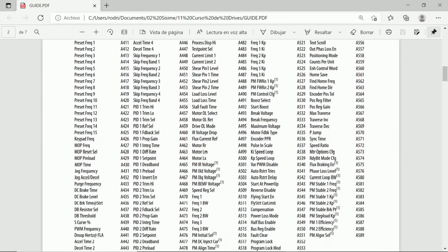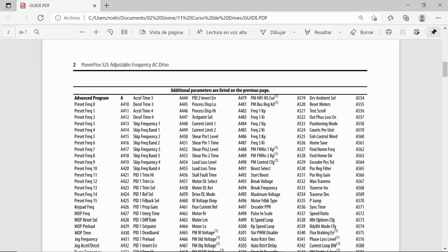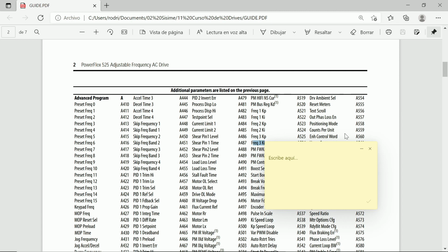Also for our PID part, which is basically our more complex part, here are gains if we wish to adjust them manually. So beyond our auto tuning, if that didn't work and you wanted to use a sensorless control, or adjust it with that control but it needs to be more efficient, then all you need to do is add the manual gains and individual gains.